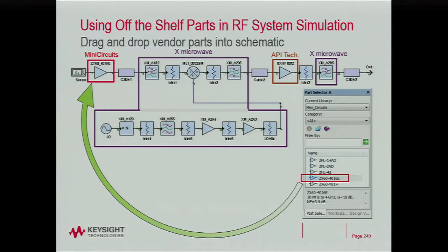And I'll talk a little bit more about this at the end, but we're taking 2.8 gigahertz at the input in the IF. The LO is about 5 gigahertz. We're tripling that, filtering it, limiting it. That's what's running into the mixer. We take the sum of that and we end up at about 18 gigahertz.